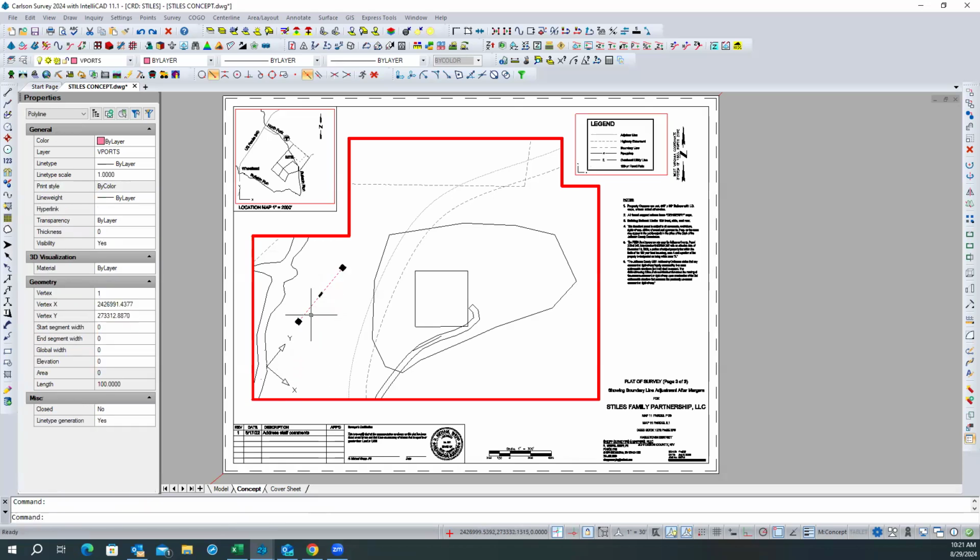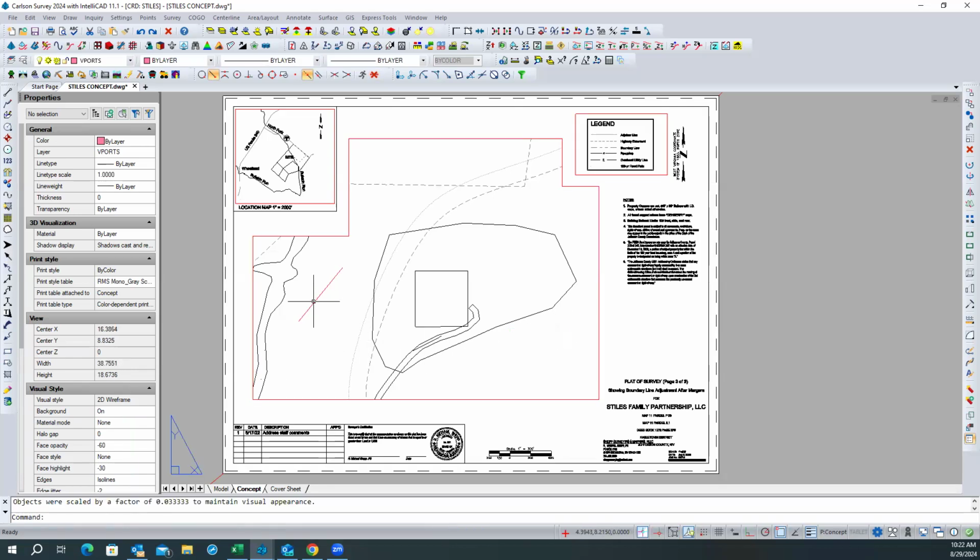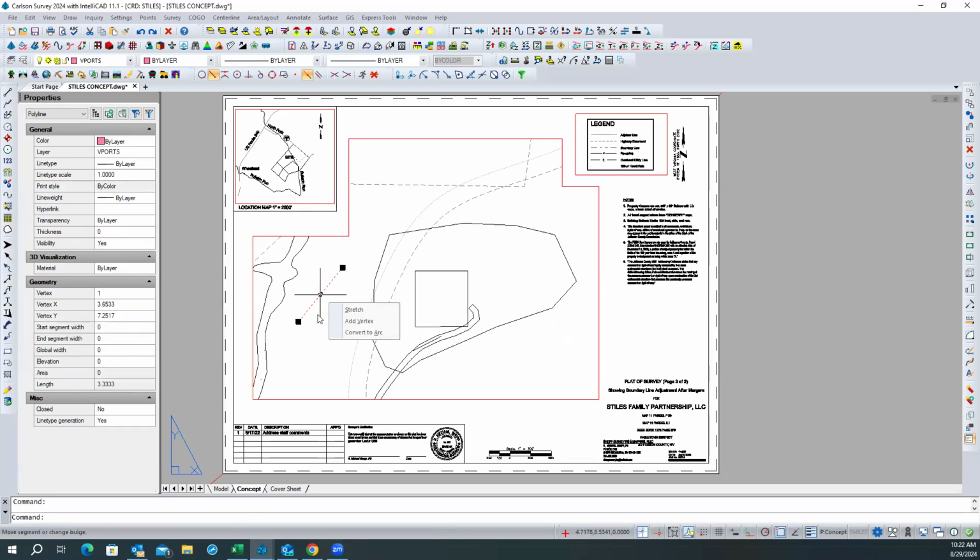Now I've got that, and I want to remember I'm in model space. So if I change space for that, CH space, I'm going to choose this. Okay, set the target viewport active, and press enter. So now, see, I'm back out in paper space. I'm no longer in there. And so now this has been moved to paper space. And I'll just move it up here.